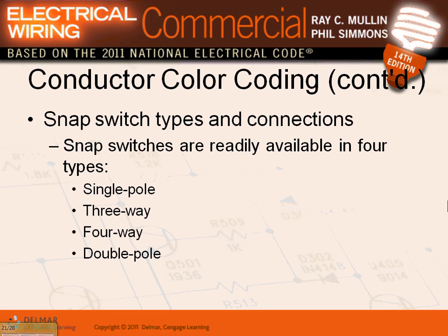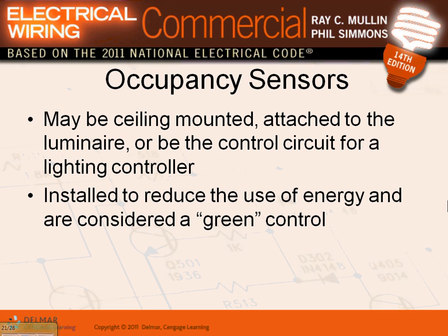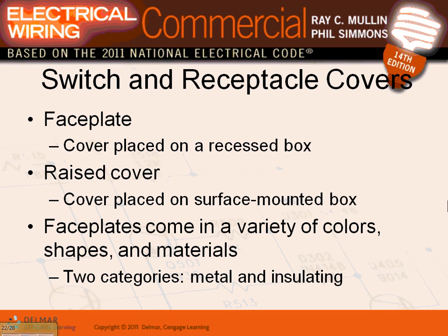Snap switches, guys, as you know, come single pole. You're looking at it, 3-pole, 3-way, or a 4-way, or double. Double means you can turn on and off two hots. Occupancy sensors. This is where you're going to wake up, guys. Next week, we're going to bring an occupancy sensor speaker. Occupancy sensors is nothing but a relay. It senses motion in the room, triggers, sends the signal, and disconnects through the relay the power circuit that's going to a lighting fixture. So we'll talk about this one a lot, guys, next week when we talk about lighting too.